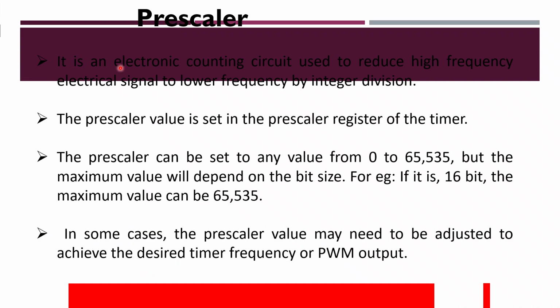Okay, so the prescaler is actually an electronic counting circuit used to reduce high frequency electrical signals to low frequency by integer divisions. So the prescaler value is set in the prescaler register of the timer.